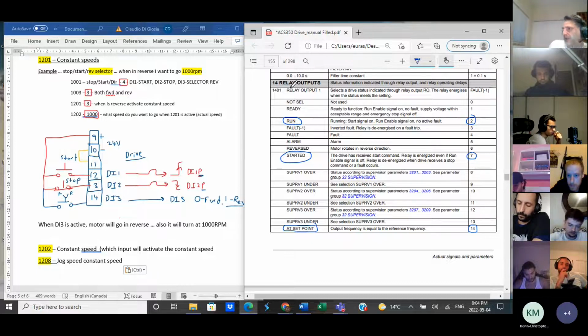We have a relay, but it's not a regular relay where we press a button and activate the coil. We have no access to the coil. There is a coil, but it is going to change the state of the contacts only when the condition that we've programmed is met, such as jog.